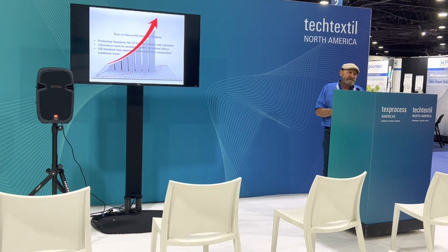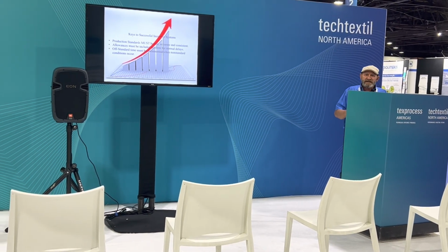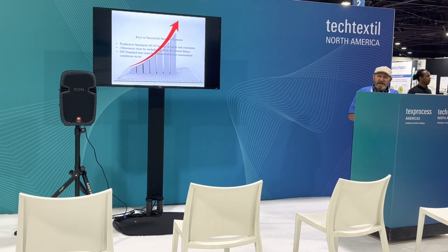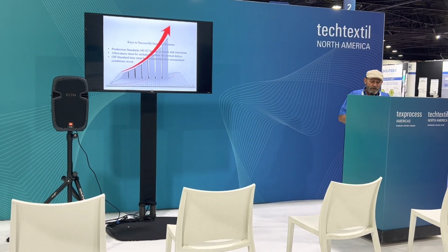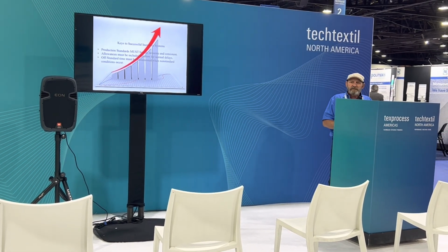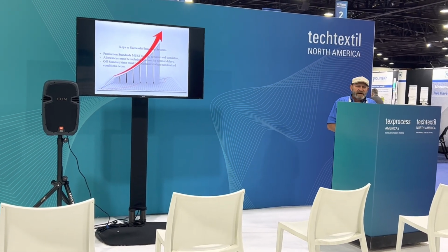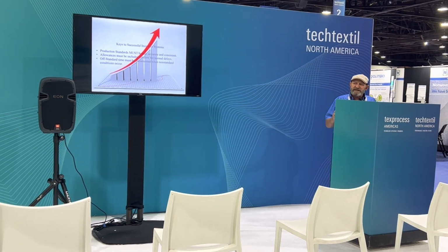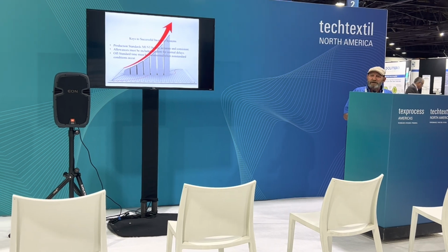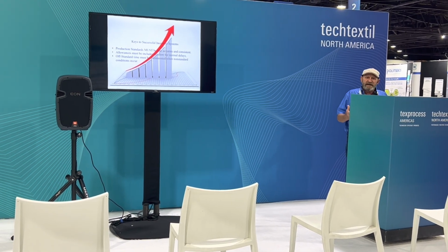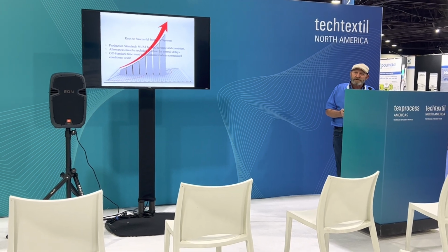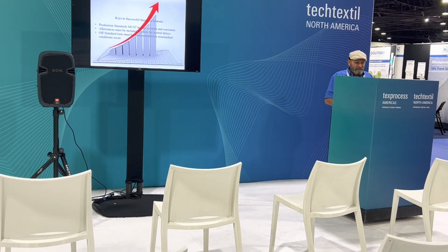So if you have lost time, you will get a report that says, hey, you have this much time lost for machine delays. The machines were broken down. The work wasn't brought out there right. You had a bunch of needle breaks, and so it breaks it down into all the different categories where you might be losing productivity. It makes it where you can actually identify where you're losing the most time, and you can focus your resources on fixing that problem.